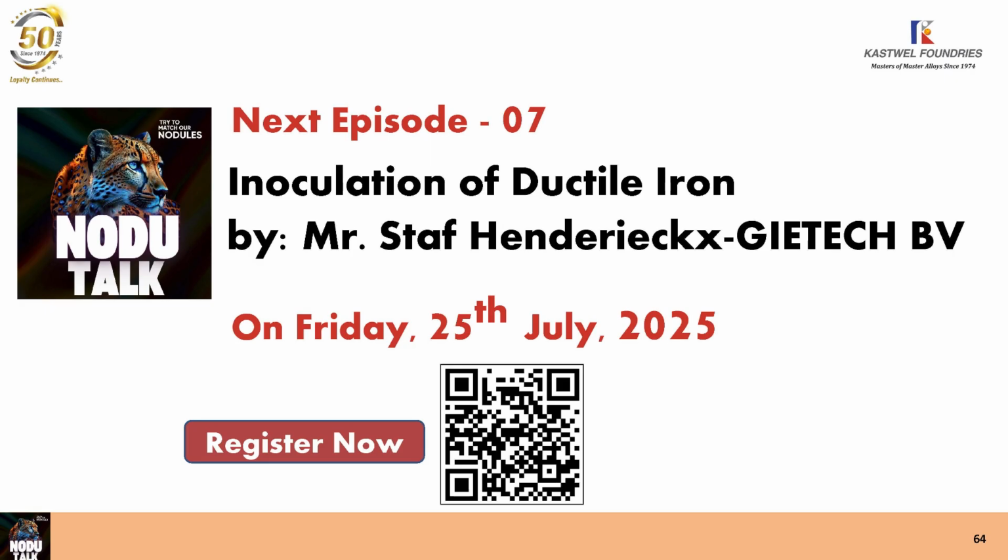That's very difficult to say, especially the tapping temperature, because in one of my books I have calculated the tapping temperature starting from the liquidus temperature of an iron. And you will see that's different in every foundry. So giving one answer for that, it's impossible. The second was the pouring temperature.